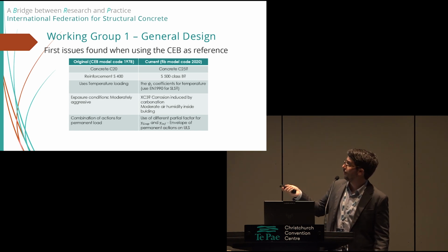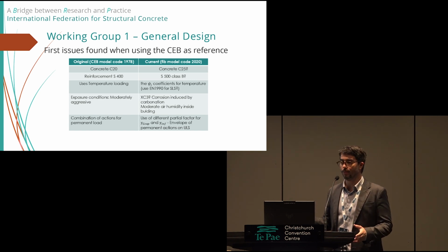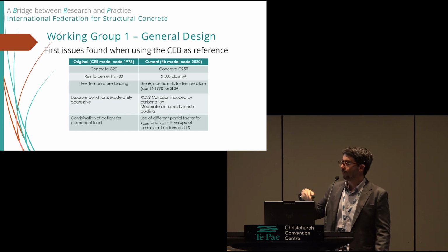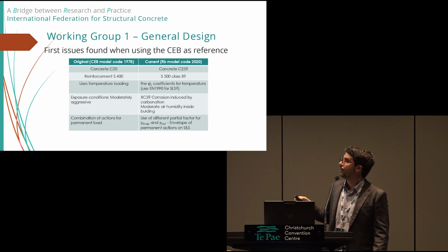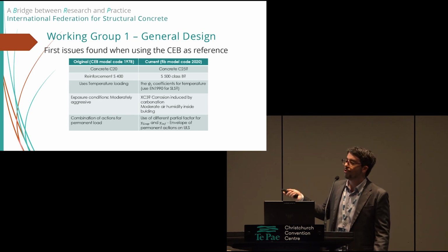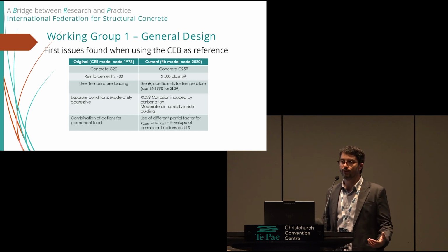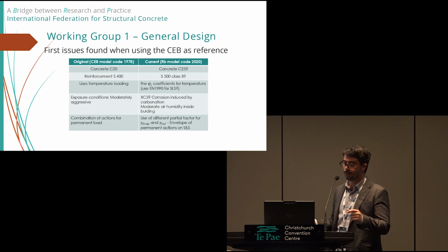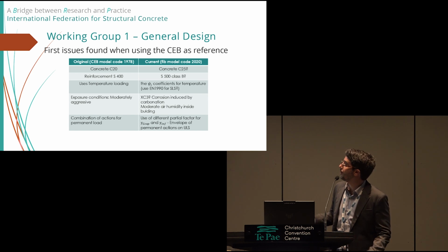They use temperature loading, which is not very usual anymore, to go to an ULS, ultimate limit state, set. Also, exposure classes were very different back then, so we are using the new updated view on that as well. We're using the new class of aggressivity.